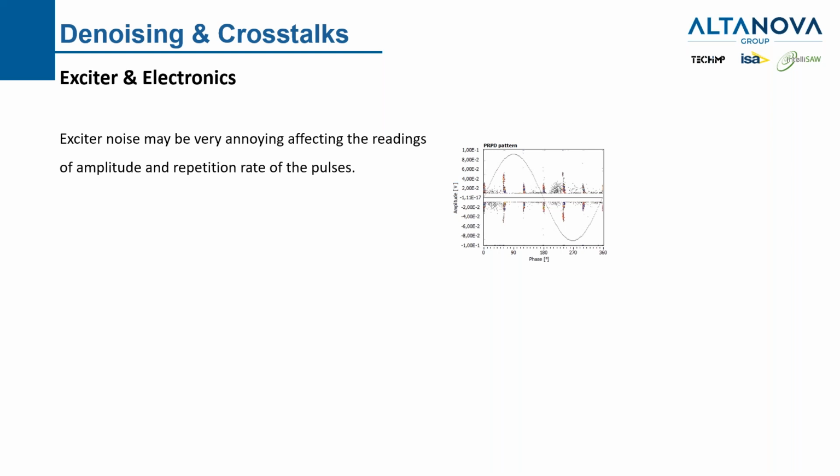But why is it so clear to me that it is an exciter noise? Because normal PD is due to the physics. We have an applied voltage that activates and deactivates a defect, so there is a correlation with the phase angle and the change. In this case, these vertical lines cover a very, very narrow angle range, and they are very, very regular. Why? Because they are clocked.